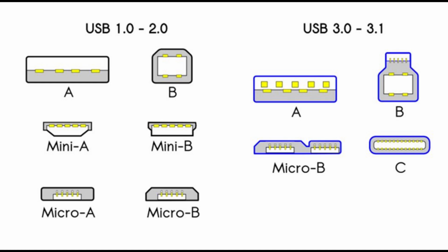USB on-the-go makes it possible for two USB devices to communicate with each other without requiring a separate USB host. Battery charging specification 1.1. Added support for dedicated chargers, host charger behavior for devices with dead batteries. Battery charging specification 1.2, with increased current of 1.5 A on charging ports for unconfigured devices, allowing high-speed communication while having a current up to 1.5 A. Link Power Management Addendum ECN, which adds a sleep power state.